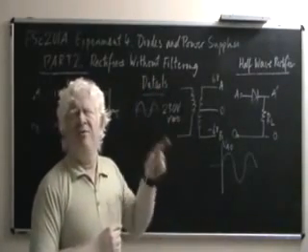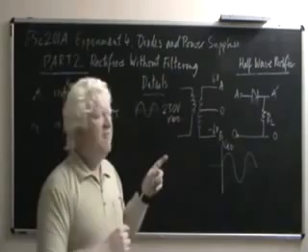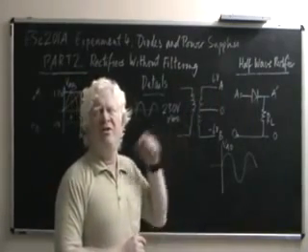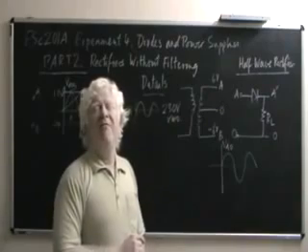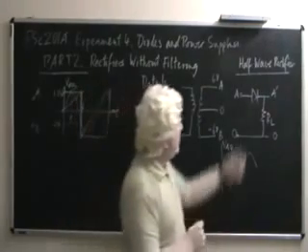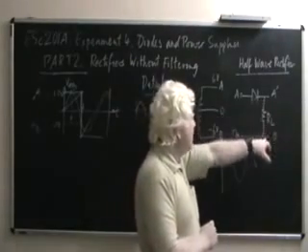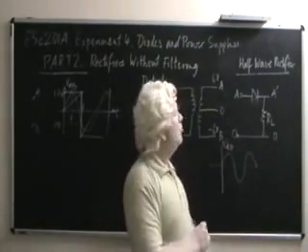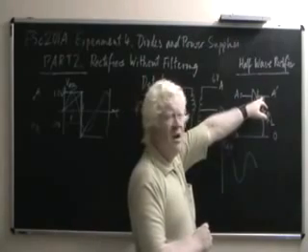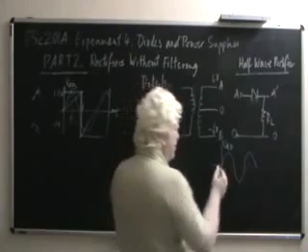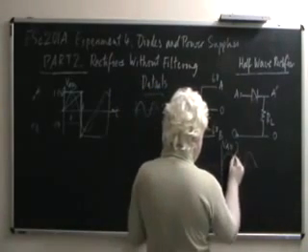A dash will be equal to A whenever A is positive, the voltage at A is positive. Whenever it goes negative, this diode acts as an open circuit. So, no current can flow through the resistor. So, the resistor's end A dash has the same voltage as O. So, what you would get here, this is VAO.